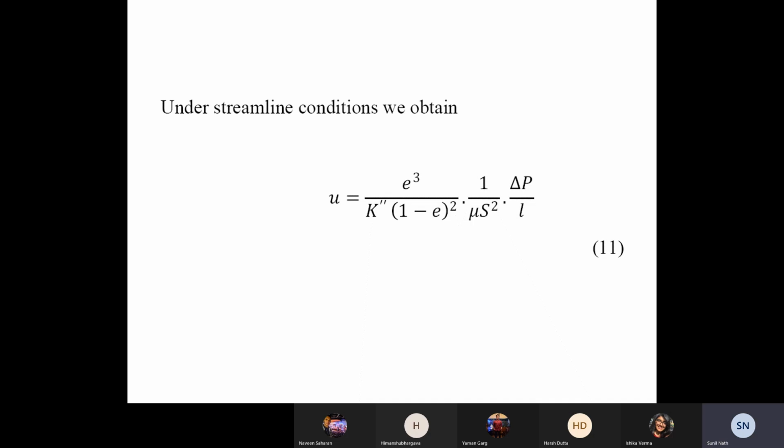what is that number? 10. Okay, you can use that. And this correlation or by equation 12. Okay, you can calculate this pressure drop once you know. No, not 12, 10, because 12 is only for streamline flow, Re less than 1. Okay, so K double prime is 5. But in general, for any other Reynolds number, you'll have to obtain the correlation, read the graph.